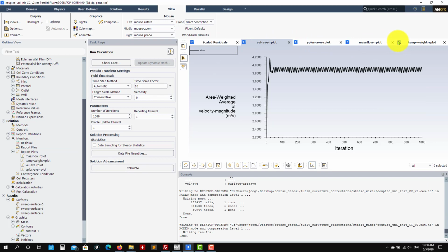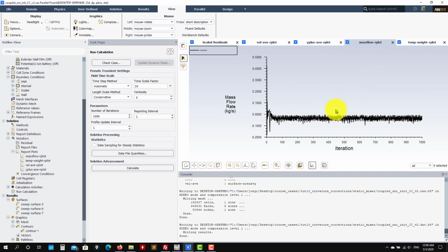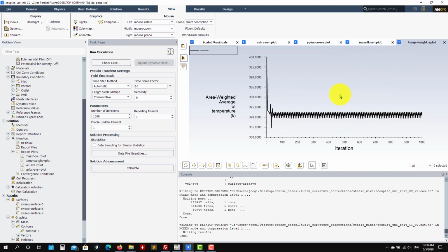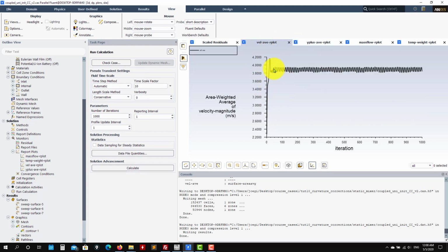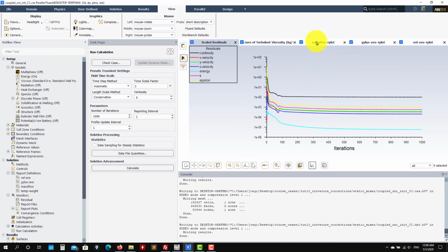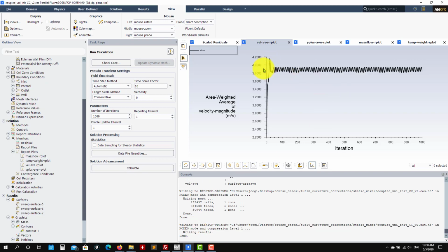So if we look at the fields, see that now this one is introducing some oscillations. It's still the average values, as you go, they might be close to the actual ones in the other one, but where you have a small time step or a small under relaxation, see that probably this one is highly under predicted. So let's go back. Let's check mass flow. Okay, so about 4.5, and then this one, see that it's highly under predicted, about 3.9.